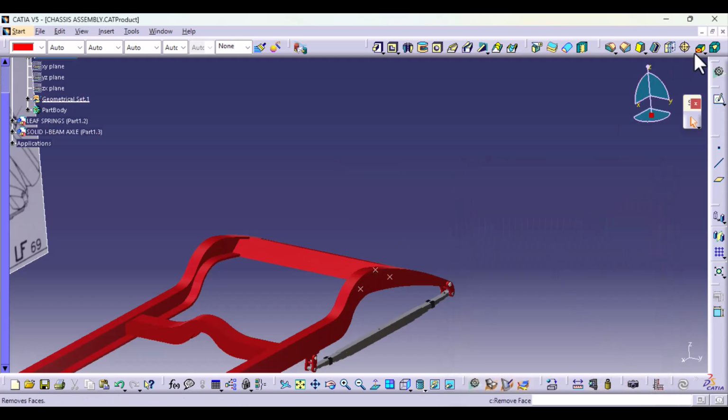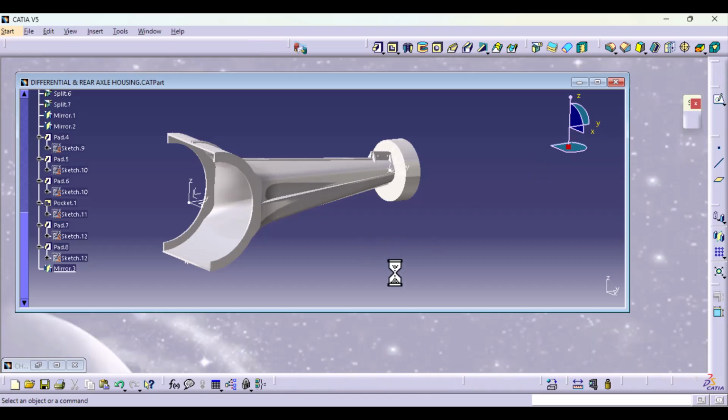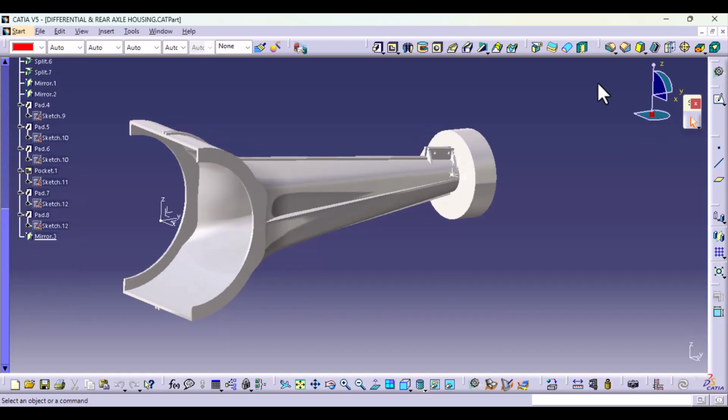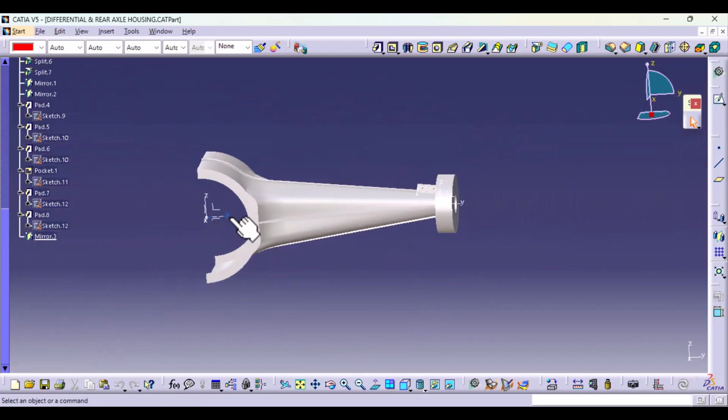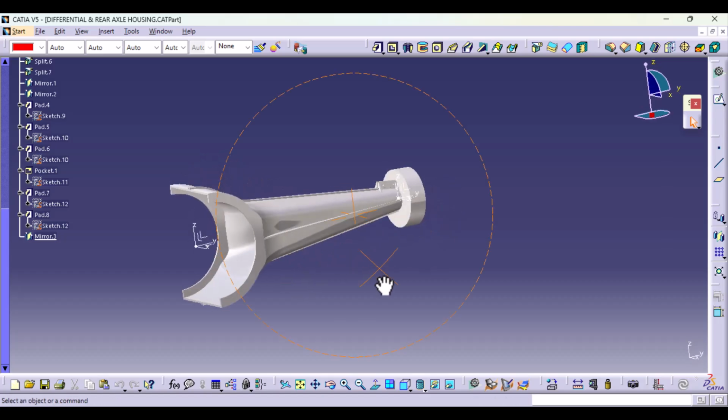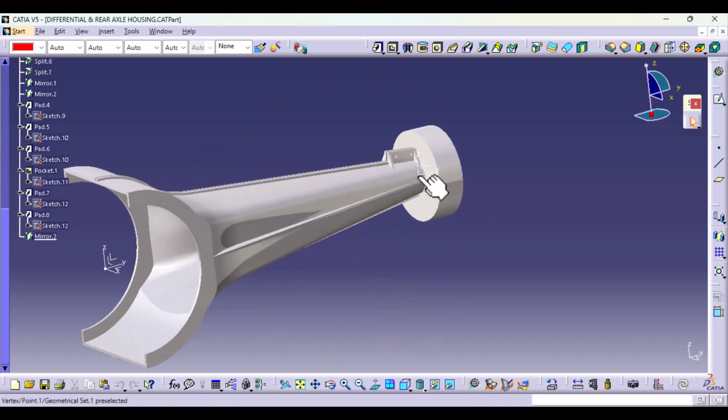So I'm just going to go back to our section. Now for this section, remember that the distance between the center and this axis or this plane is 620. But you see our attachment needs to be at 480, and that's why we wanted to measure that, because if we create the attachment here, it's not going to align with our chassis.